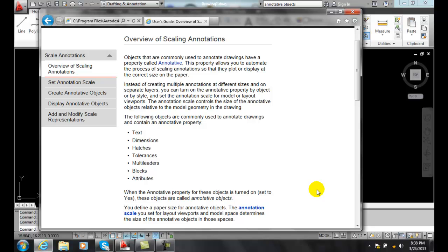We're going to have to either enlarge it or reduce that object to fit it on a piece of paper. We typically have been dealing with this in model space, but now we've been learning the process of layout tabs, and those layout tabs mimic the sheet of paper. So what we'd like to do then is have our floating viewports control the scales in our layouts.